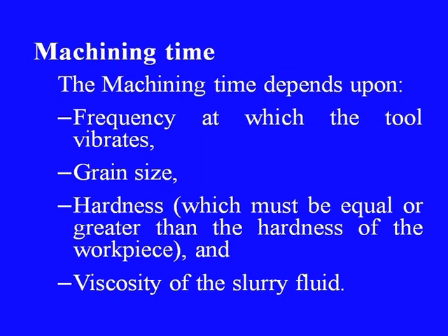Then, of course, the hardness, which must be equal to or greater than the hardness of the workpiece, and then the viscosity of the slurry fluid. Regarding viscosity, we have already discussed that lower viscosity generally gives rise to a better material removal rate.